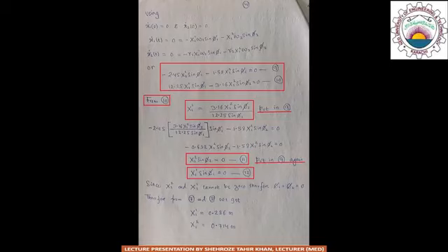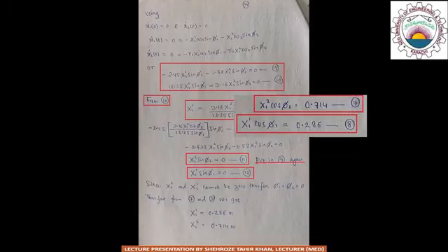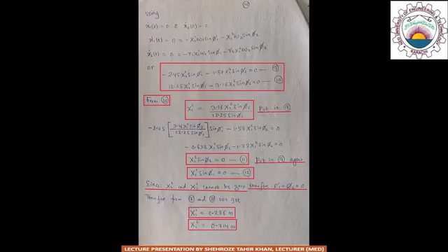Since from equations 7, 8, 11 and 12 it is evident that the mode shapes cannot be 0, therefore if we take the phase angles phi1 and phi2 equal to 0 in equations 7 and 8, then the actual values of mode shapes x11 and x21 will be yielded as follows: x11 is equal to 0.286 meters and x21 is equal to 0.714 meters.